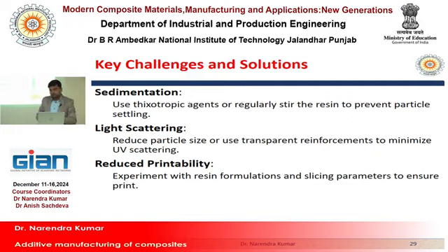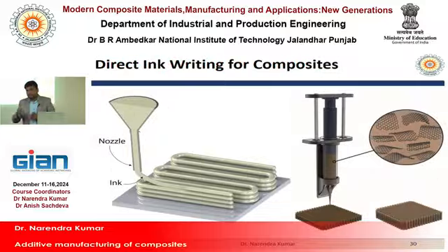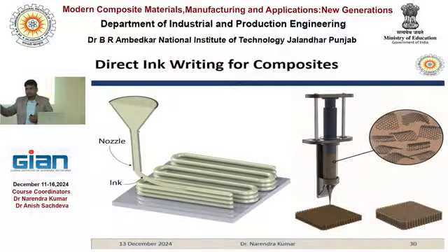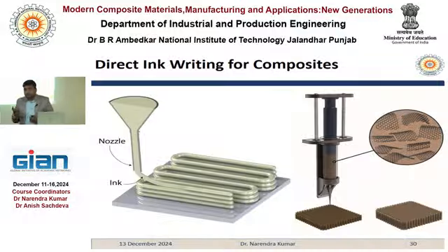Another process that is also liquid based is direct ink writing, right? This process we have also developed in our lab, and the part that I have shown to you, the copper and epoxy printed component, we made through this technique only, direct ink writing. Direct ink writing means we prepare the resin in ink form, then with the help of a syringe we deposit the material on the platform.